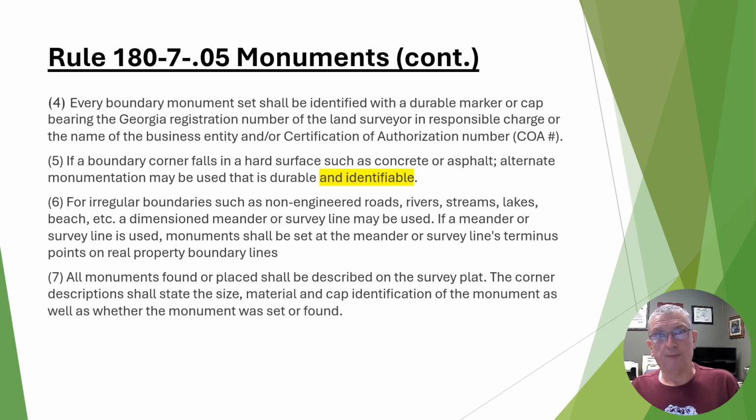If it's a swamp and we've used aerial photographs, remote sensing, old topo maps, old surveys, and this is where we think it is, but the swamp's 400 feet wide, prove me wrong, but here's where we think it is, then at least we're putting people on notice, indisputable language, that, if you drain the swamp and figure out where the thread of the stream is, it might be somewhere different, and it's a riparian boundary, and there we go.